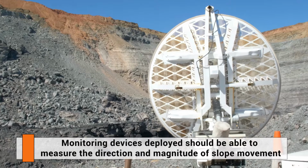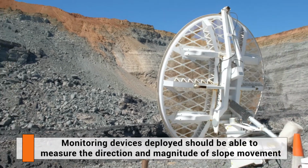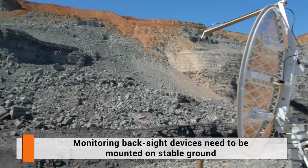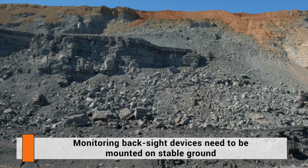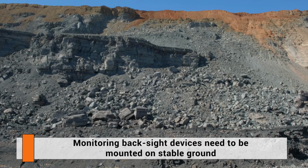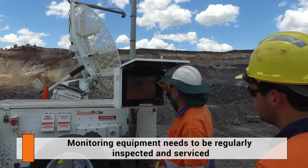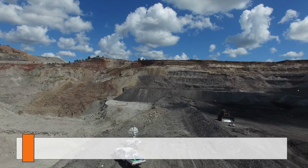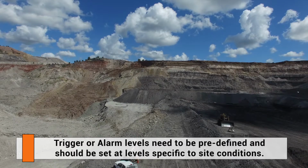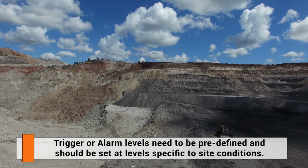Monitoring devices deployed should be able to measure the direction and magnitude of slope movement. Monitoring backsite devices need to be mounted on stable ground, otherwise false or misleading measurements can be recorded. Monitoring equipment needs to be regularly inspected and serviced to ensure it is operating as required. Trigger or alarm levels need to be predefined and should be set at levels specific to site conditions.